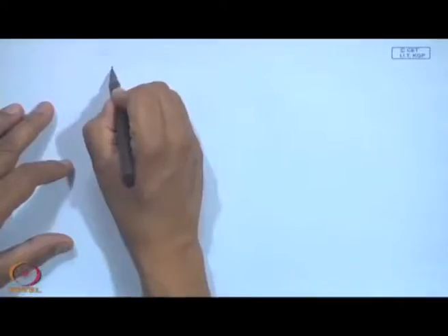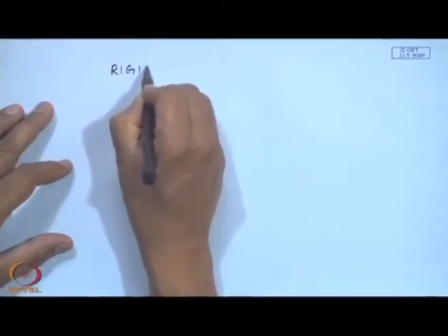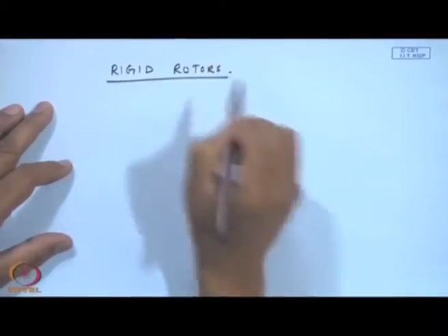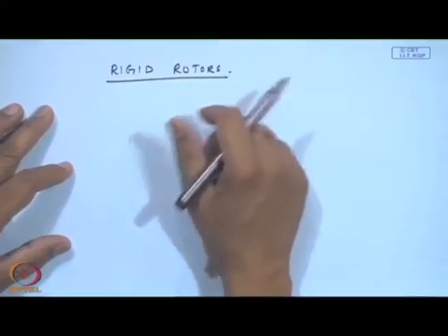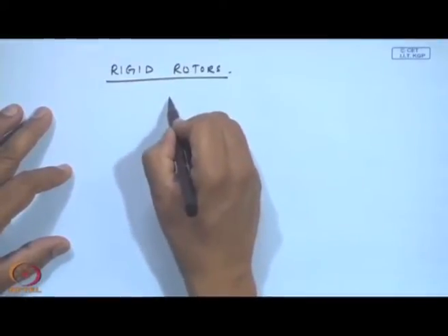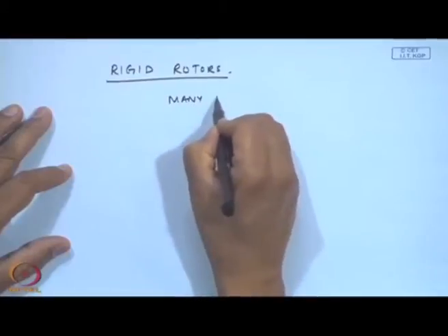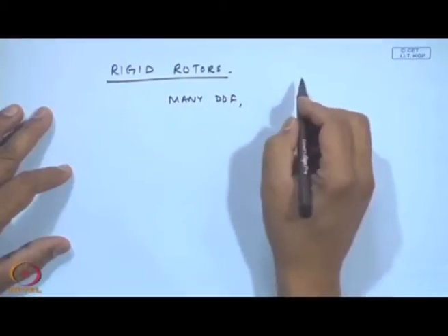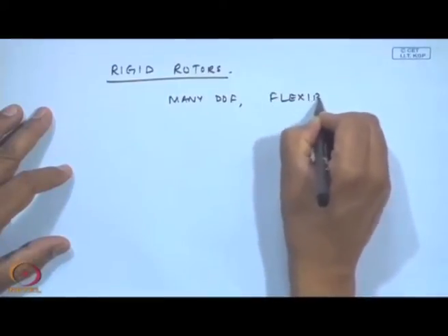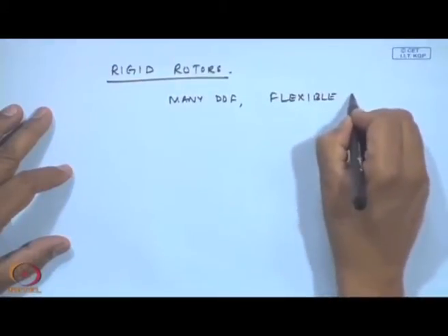Now, of course, one of the fundamental assumptions we are making in this balancing is that these are rigid rotors. But you know from our class on rotor dynamics that the rotors have many degrees of freedom and need to be treated as flexible rotors.